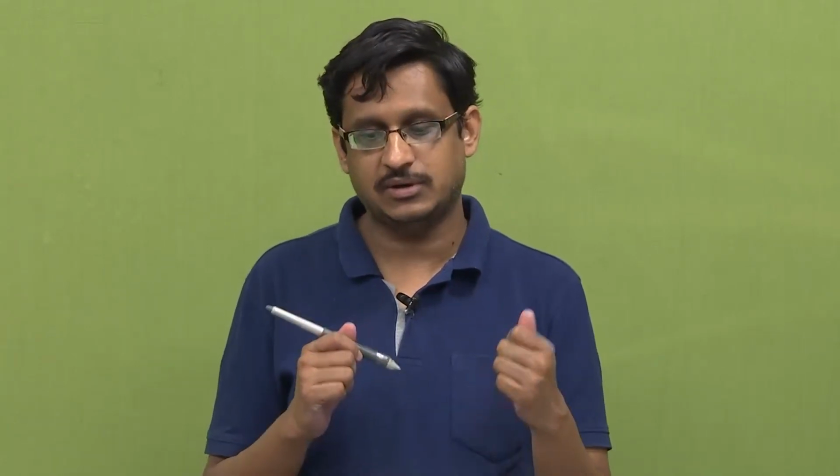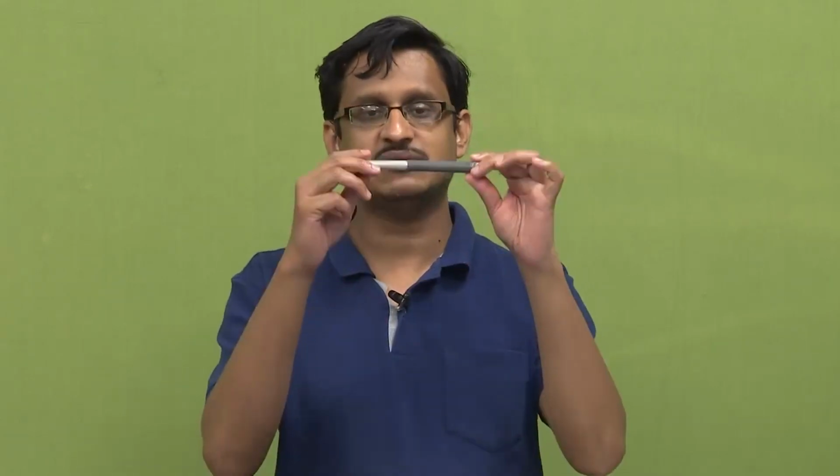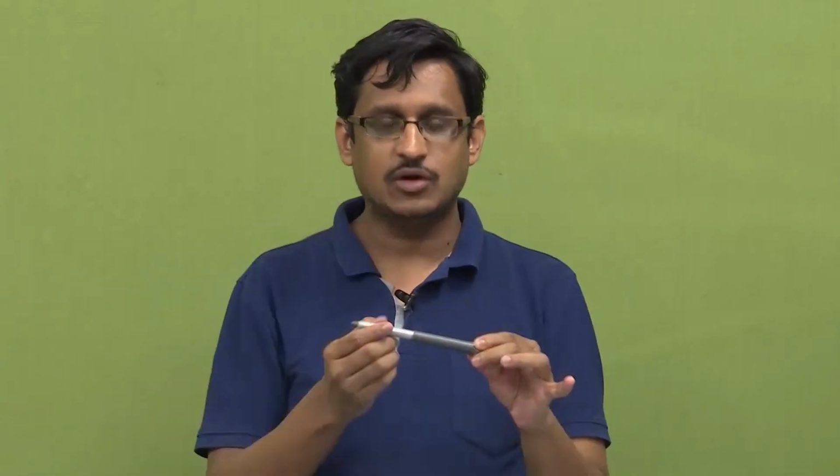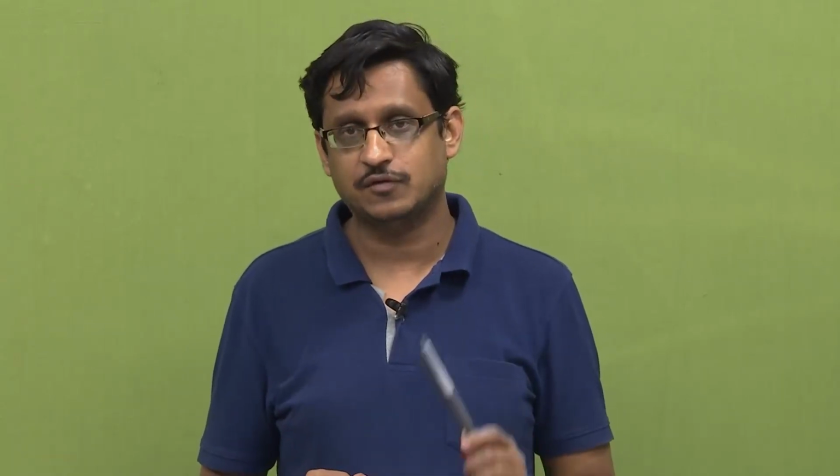How does the optical fiber change the power? Because there is going to be absorption, right. The optical fiber, if you remember the structure that I showed you in the first module, is actually something like this. It has a core, it has a cladding, then there are jackets, and all this is not some kind of a hollow tube, they are actually solid materials. They are made out of fused silica, and you know that no material will be completely loss free.